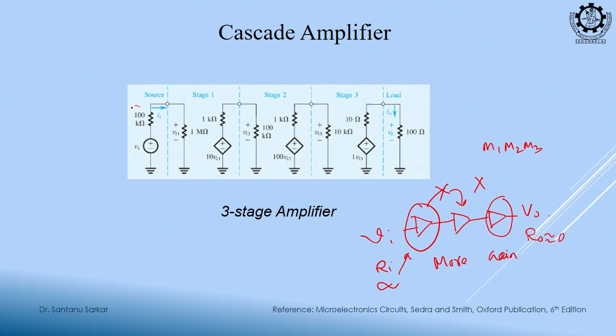You see that the internal voltage source resistance is 100 kilo ohm. Is it a small value or a large value? Large value. Does it satisfy that my voltage source should have 0 resistance? No. Then the other constraint is that the load resistance should be much higher than that, so that we can neglect it. What is the load resistance for this source? 1 meg ohm, so it is relatively higher.